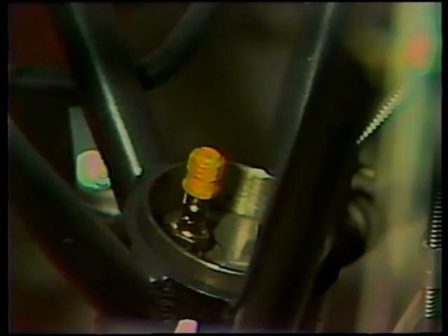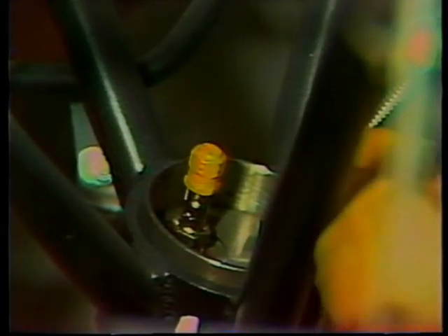Two of the various types of high-pressure air valves used on shock struts are the standard and the winterized types. The standard air valve contains a valve core and has a 5/8-inch swivel hex nut. The winterized air valve has no valve core and has a 3/4-inch swivel hex nut. Remove the protective cap from the air valve, exposing the valve.